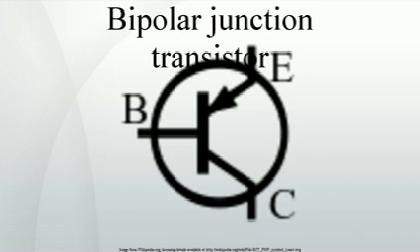As shown, the term x in the model represents a different BJT lead depending on the topology used. For common emitter mode the various symbols take on specific values: x equals e because it is a common emitter topology, terminal 1 equals base, terminal 2 equals collector, terminal 3 equals emitter, Ii equals base current, IB, Io equals collector current, IC, Vi equals base to emitter voltage, VBE, Vo equals collector to emitter voltage, VCE.